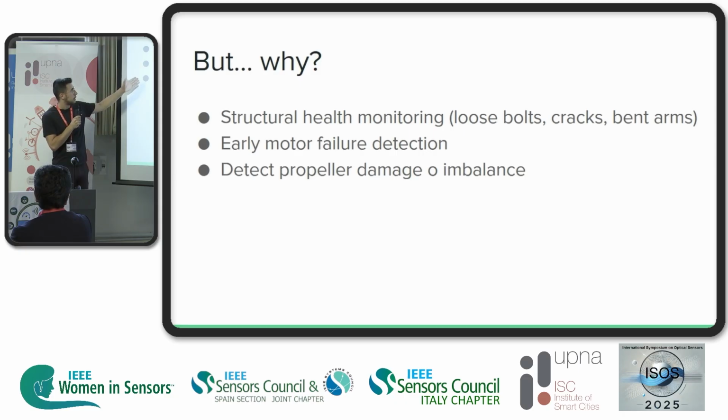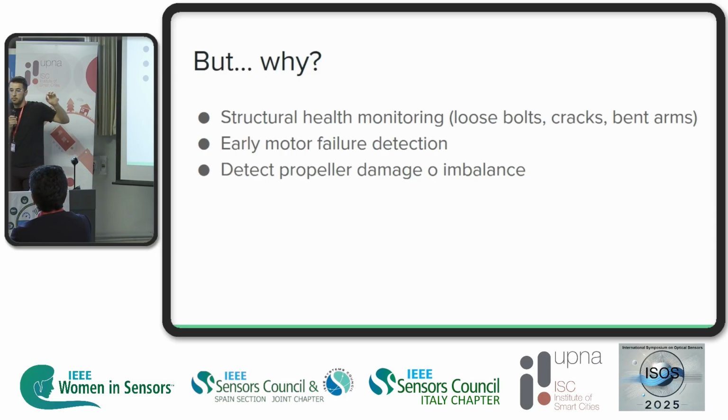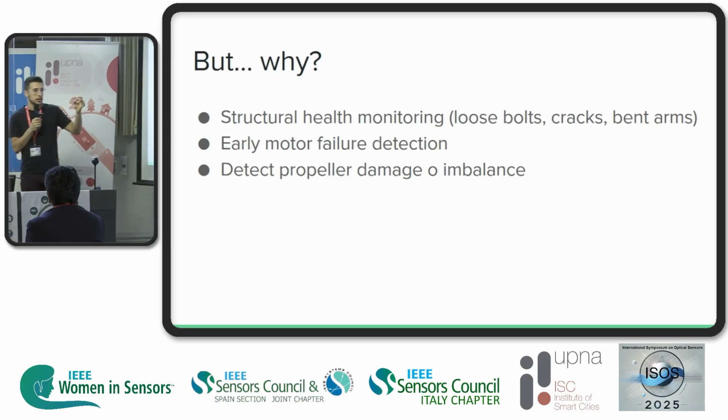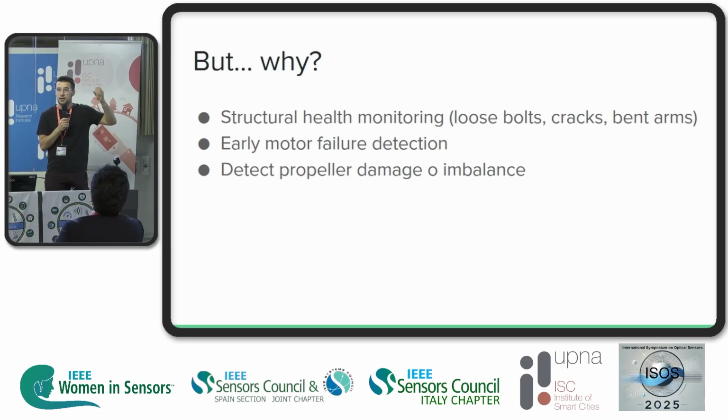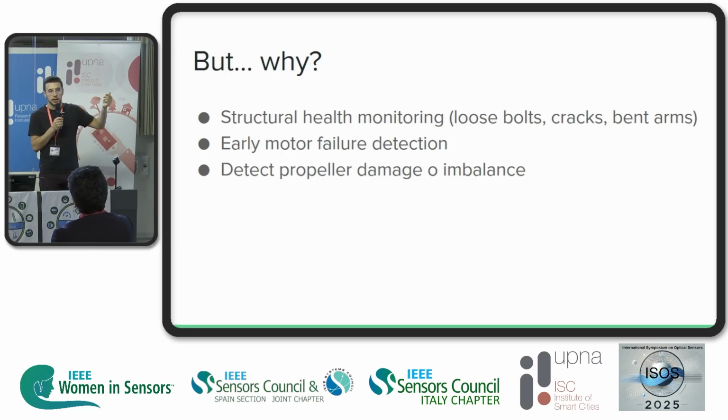We would also like to detect motor failure. So if a motor is about to fail, maybe we can detect that early so that we can prevent the aircraft from crashing. And also we can detect, for example, if a propeller has hit some tree or some branch in the case of power line inspection and has caused some damage.